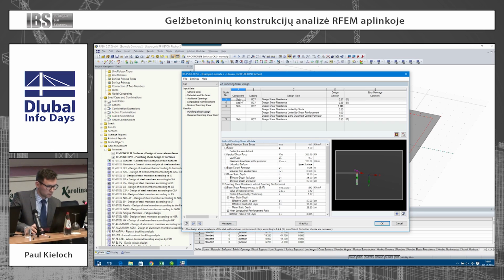Yeah, and the model directly switched to table 2.1 with the punching shear design and the design criteria. So we can just click through the single results here. You see 0.87 on node 5, 0.89 on point 6, and on point 9 I also got 0.85. So on these 3 points, with the defined longitudinal reinforcement, the punching proof is fulfilled.